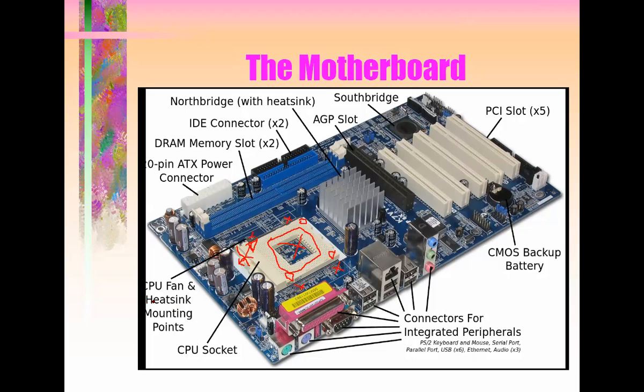The reason why we need the heatsink is so that when heat is produced from the CPU, the heat gets into the heatsink, then the fan will blow away the heat. So there's allowance for air to circulate so that heat is taken away from the CPU so that it doesn't heat so much. I realize that if your CPU fan is no longer working, it will not take more than a minute before the computer shuts down.